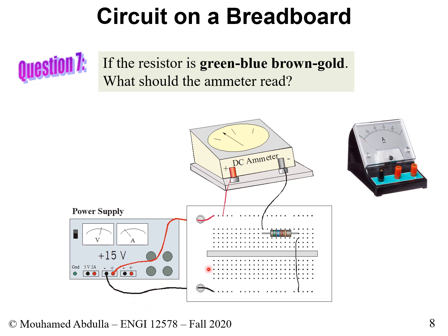And you also have your breadboard. So you are feeding your breadboard on this side, on this line, which we said is all connected together with the positive, and on this side with the negative. And from here, you could pick it from anywhere. It's the same node, right? They're all connected together. So we pick it from here.